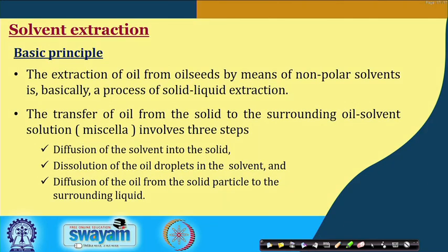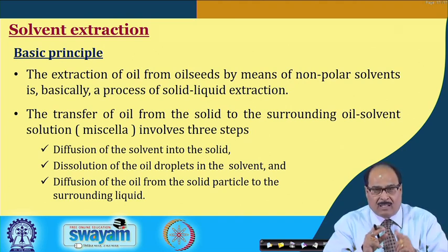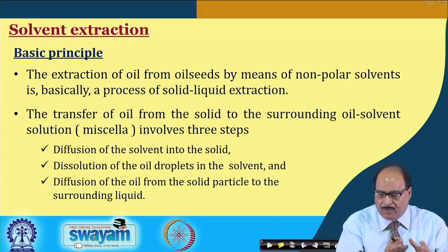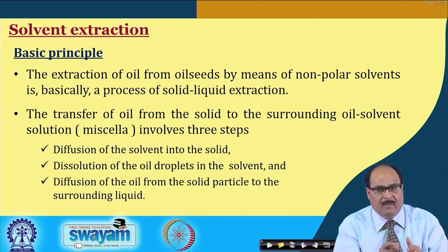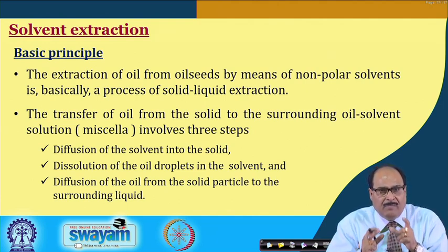The extraction of oil from oil seeds by means of non-polar solvent is basically a process of solid liquid extraction. It is the transfer of oil from the solid to the surrounding oil solvent solution, which is normally called miscela. It involves three major steps.